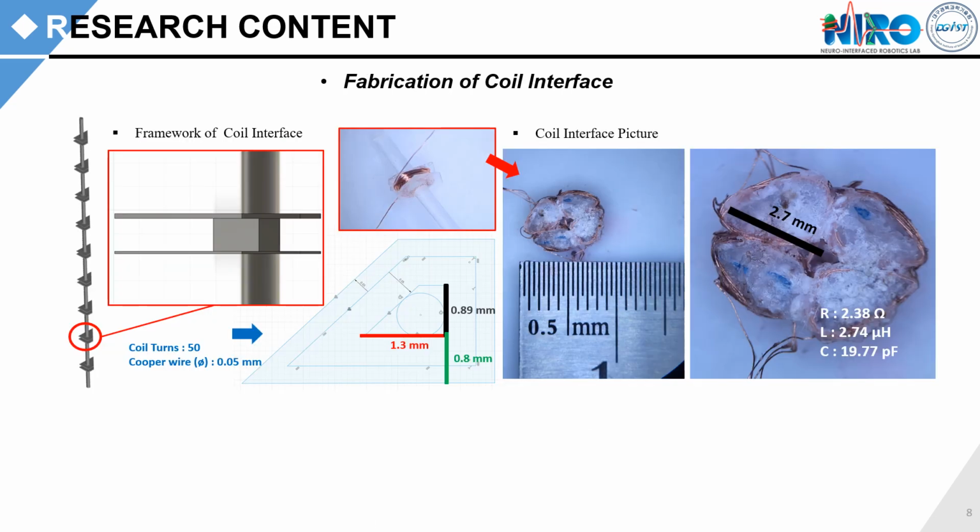The coils were fabricated as follows. We made the coil-shaped model using a 3D printer and wound the coil by hand using copper wire of 50 micrometers in diameter. The size was determined to be 0.75 size factor level because 0.5 size is too small to make precisely by hand. The fabricated coil is shown in the following picture. Wires were wound around each mold by 50 turns, considering the direction of the current.